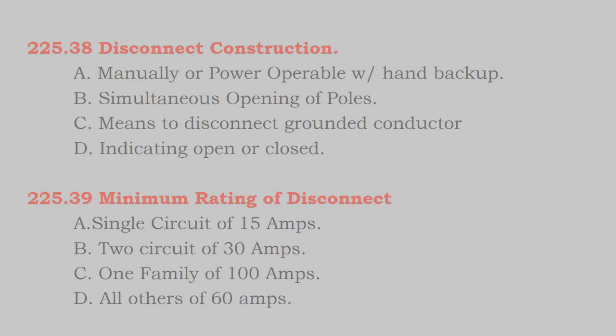And those motorized breakers right now cost about 120 to 130 bucks. But the rules on those motorized breakers, if they're going to qualify as the disconnect, they also have to be hand operable. So sometimes the little tab will stick through the motor and you can wiggle the tab back and forth by hand, but the motor will still also separately operate the breaker. Otherwise, they need to be separate.